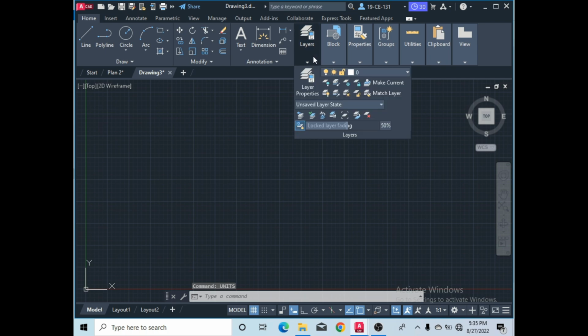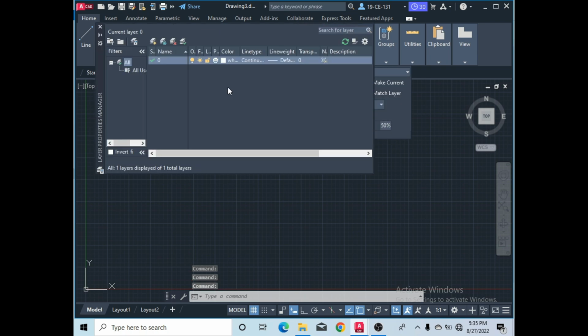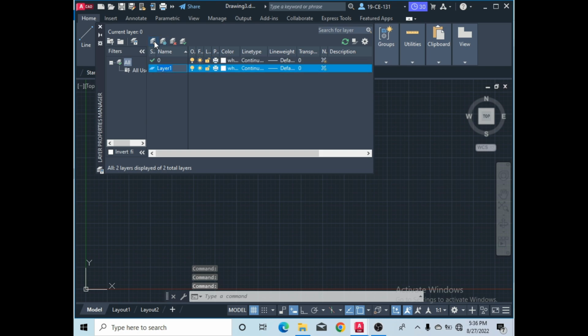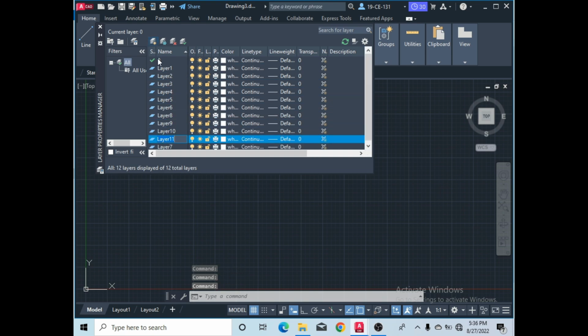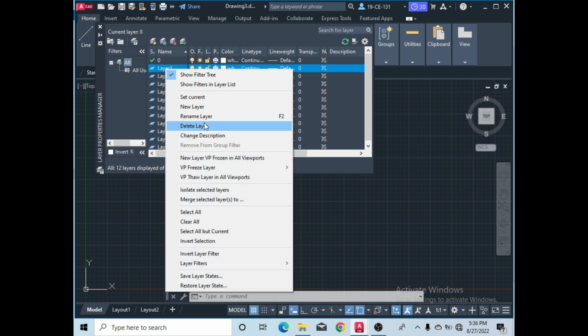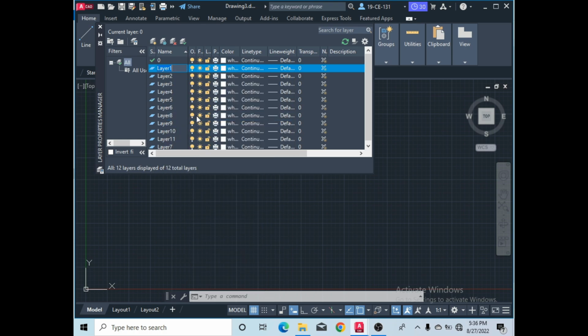And then the second option, go in layer and click on properties of layer. A new window will open. Now click on new layer, and create more layers. So now I will draw the walls. I should rename this to walls. So press enter, this is named. Then I will name this later.